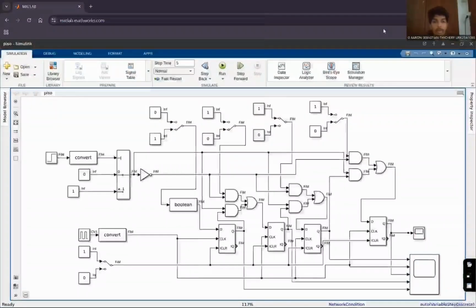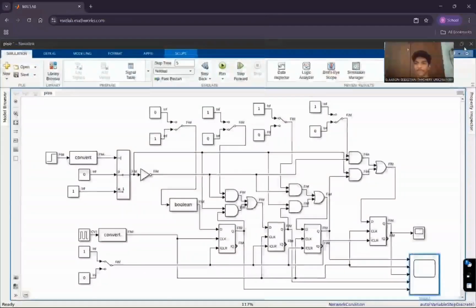The two real-world applications for PISO circuits are serial data transmission and reading multiple switch closures into a single multiprocessor. As for SISO circuits, the two real-world applications would be a delay line and data storage and retrieval within digital circuits.